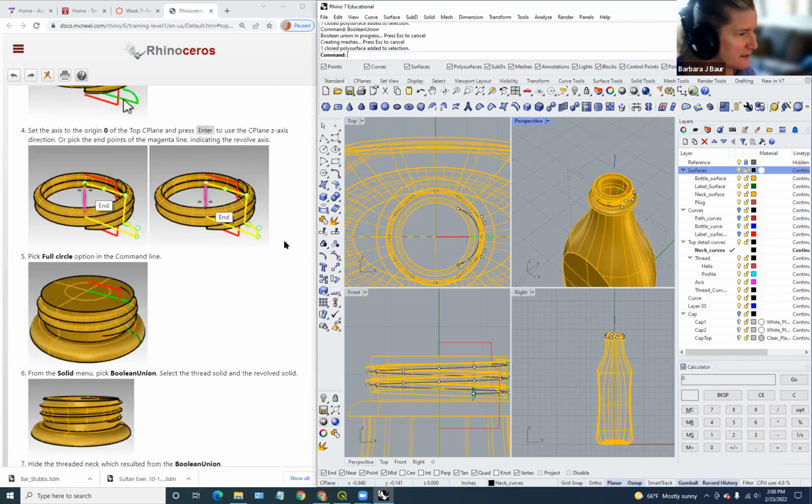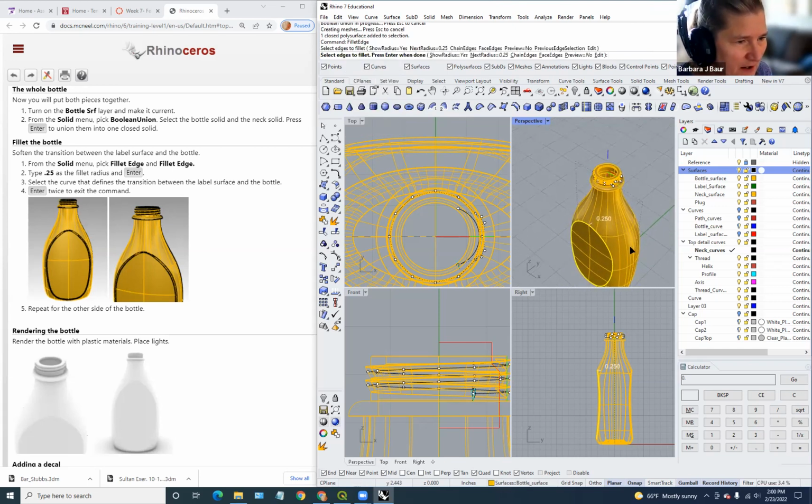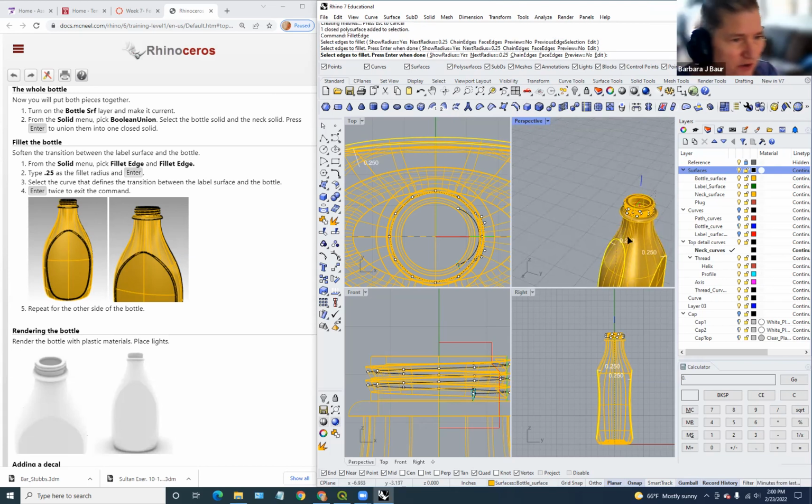The last thing that you want to do is fillet the edge, F-I-L-L-E-T. Let's spell right for first, Barb, huh? Fillet edge. Okay, we're going to grab this edge here, and then we're going to work with the edge on the other side. Because I did this earlier, it actually still had the measurement in. Normally it would be 1.